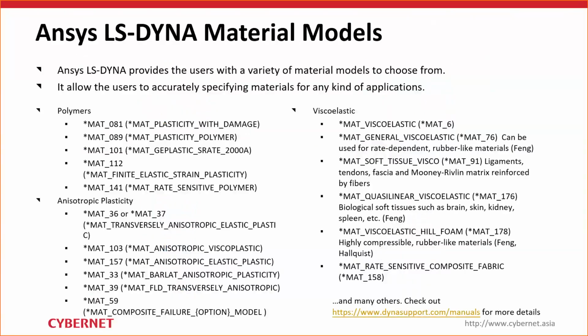Now let's touch a little bit about the material models available with LS-DYNA. When we're dealing with a problem with a high level of non-linearity, it is important that we specify the materials that we are using accurately. In cases such as a crash test, the material plasticity needs to be defined in order for the crash results, where the crumpling of the structure deforms permanently, to be captured accurately.